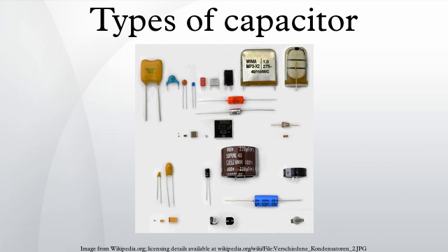Data sheets for film capacitors specify special curves for derating AC voltages at higher frequencies. If film capacitors or ceramic capacitors only have a DC specification, the peak value of the AC voltage applied has to be lower than the specified DC voltage.